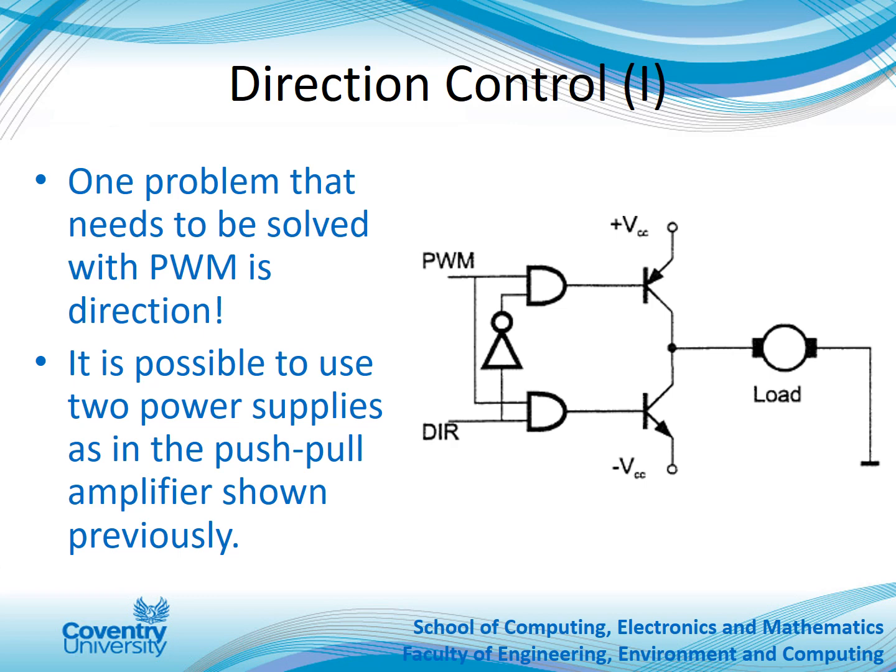In one situation, this transistor will be on and this transistor will be off, and you'll get a positive to ground path like so. That will allow the motor to spin in one direction. Then in the other situation, when this one's turned off and this one is turned on, current flows from a high potential to a low potential, so there's your negative supply, there's your ground, so you'd get the current going like that. You would get the motor spinning in the opposite direction, so that gives you your directional control.